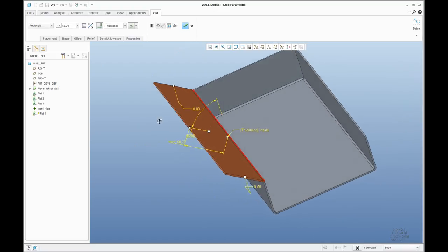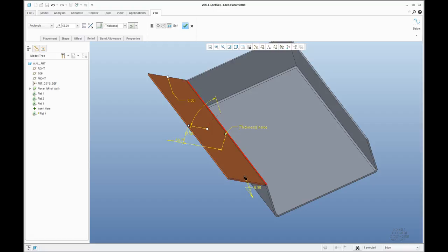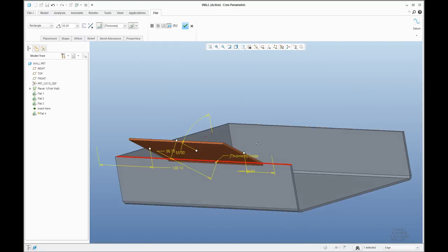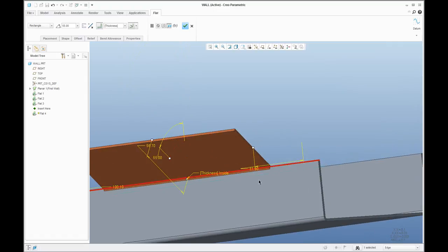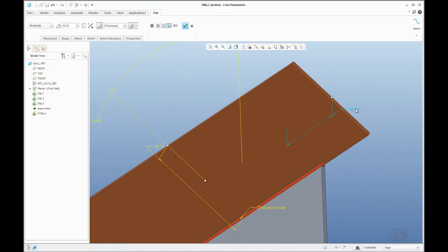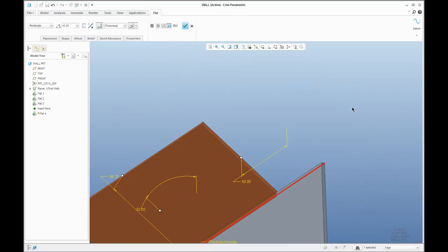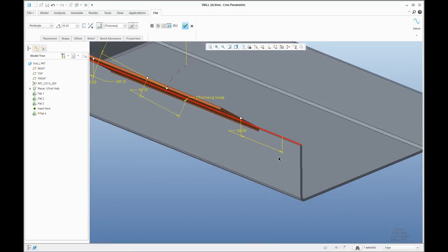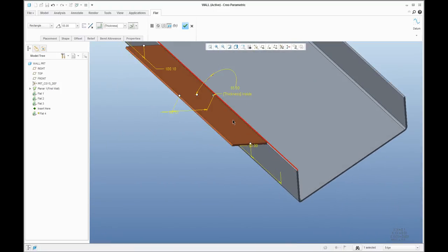time. And what about relief? You can see here, if I use the function with the dragger, and I change it to some dimension here, positive dimensions mean add material. So you can see here the system will add material. If I select a negative value, the system will remove this material here.